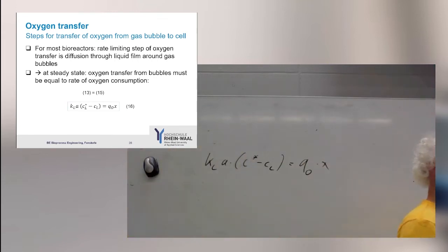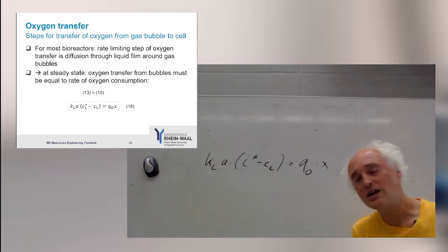Because if we dimension a bioreactor, and of course we are aware that q_O2 could vary, but if we pick a reasonable q_O2 value and assume it is constant, and we have certain conditions, we can estimate, if we end up with a certain biomass concentration at the end, what kLa value we need in order to guarantee that.